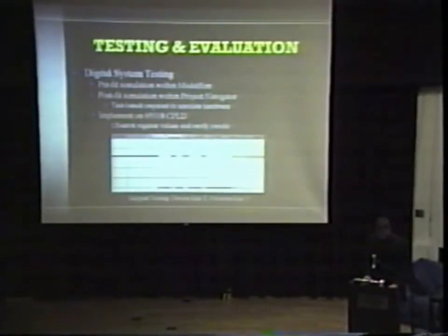In testing the system, the digital went through several phases. The pre-fit simulation within ModelSim, a post-fit simulation within Project Navigator. These both required a test bench to simulate the hardware. After simulation was successful, it was then implemented on the 95108, and the register was observed via a logic analyzer. As you can see,